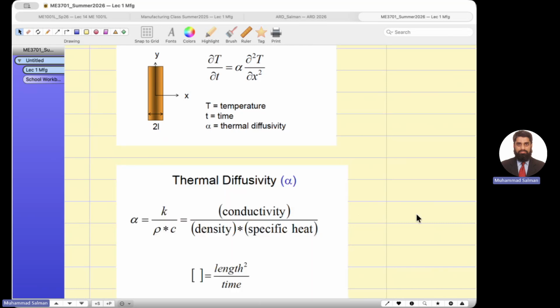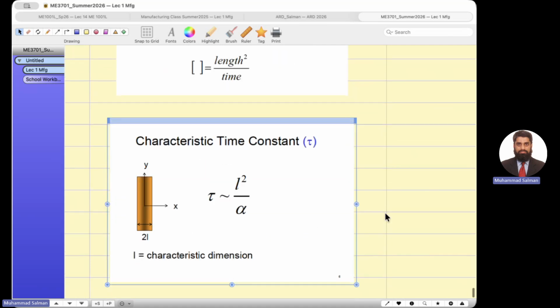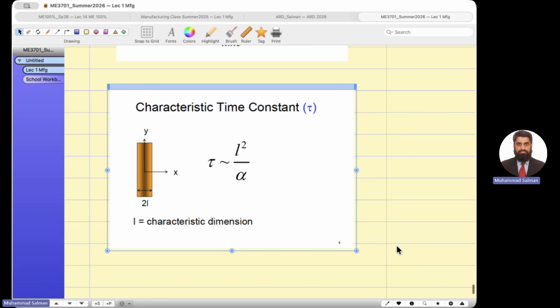But if you have not taken it, this much is sufficient to prove it. Conduction equals convection. At least you know that m c delta T equals h A delta T times dt. Now this is just the thermal diffusivity, and this is for estimation. You see my point, guys? For estimation, the time required to solidify or transfer is L squared over alpha.